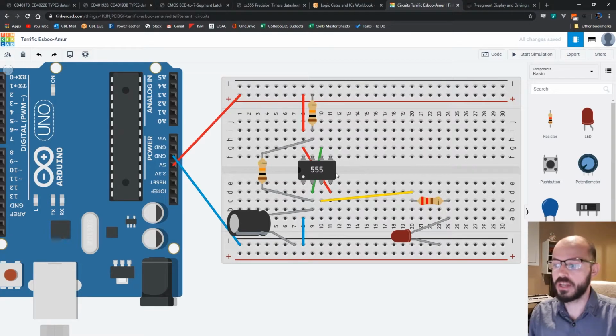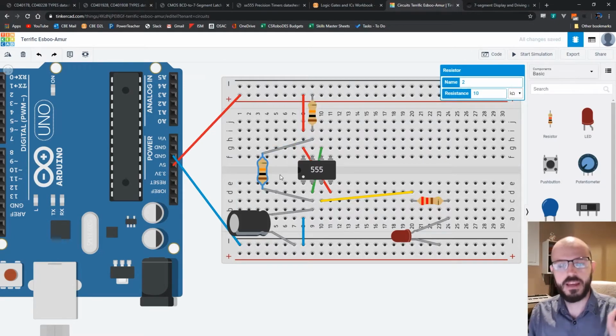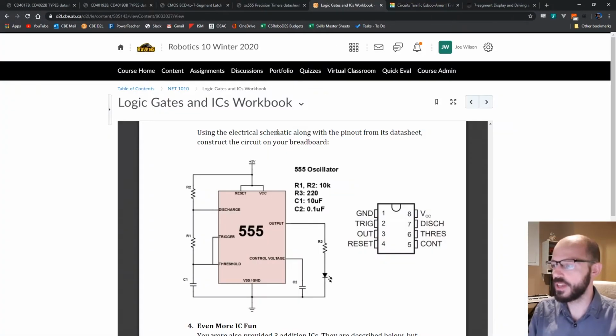And so you can make a square wave with the 555 and send that into a little speaker and have that tone coming out. And then if you have a potentiometer hooked up like we just showed, you could change that tone with the potentiometer. Lots of cool things you could do with that. You could make a little synthesizer keyboard out of just a bunch of 555s hooked up to buttons and just getting the exact right resistance in here to make each specific tone. So there's a neat idea. But what else can you do with ICs?